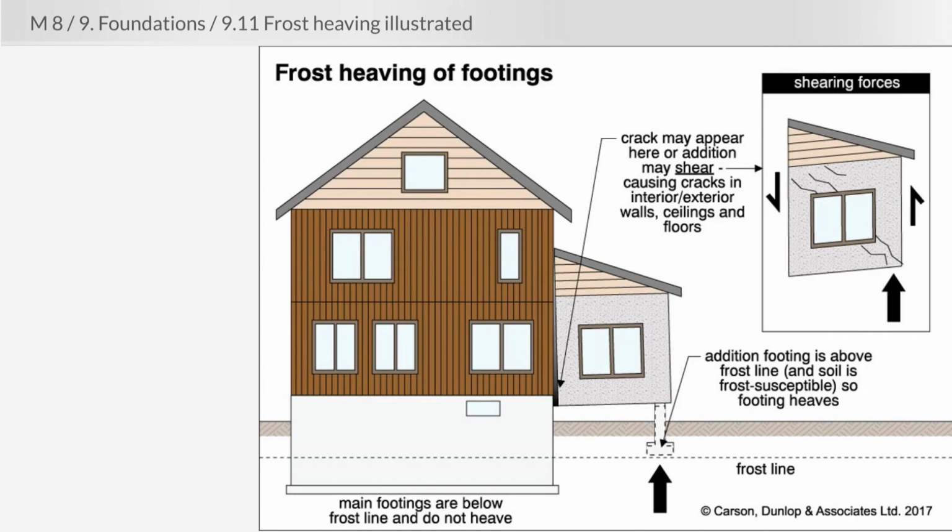In cold weather climates where, in the winter months, the ground will freeze, there is always an accepted frost line. And that's listed in all the local building codes. Anytime a home is built, the footings are required to be placed below that accepted frost line. Now, the reason I say it's an accepted frost line is because it's determined based on historical data.